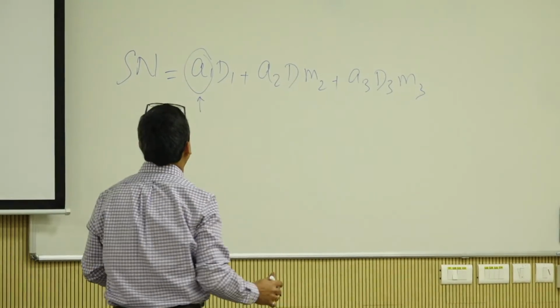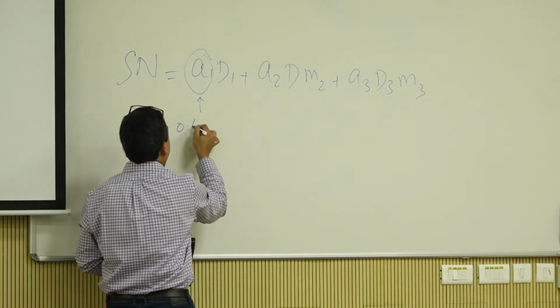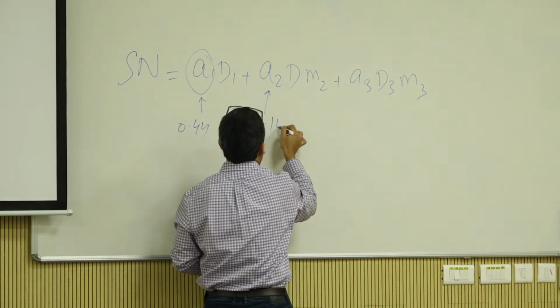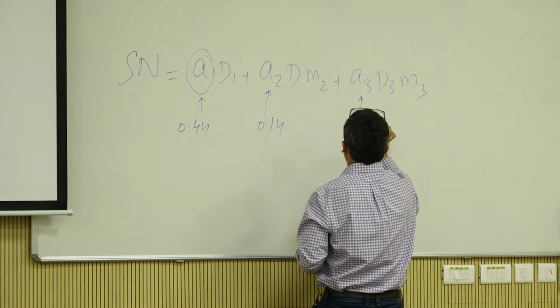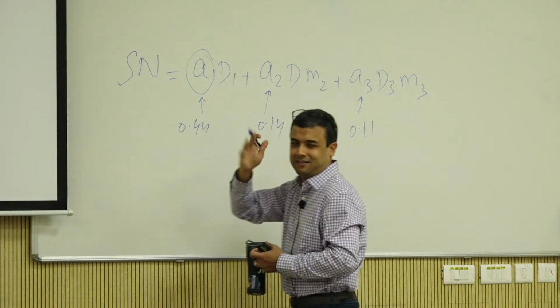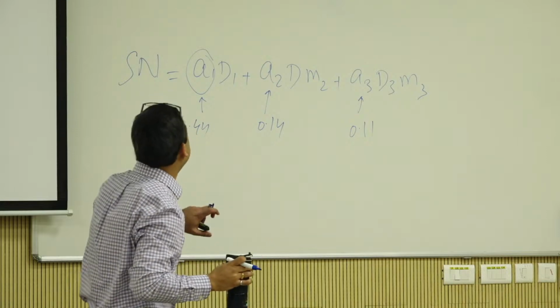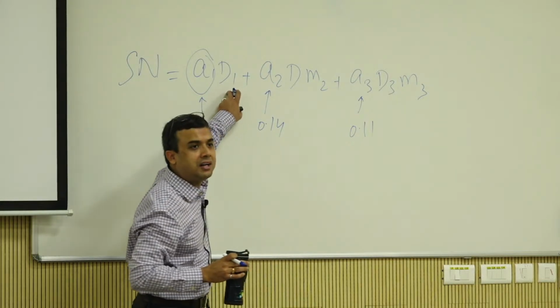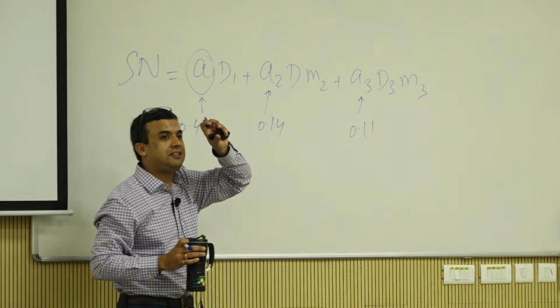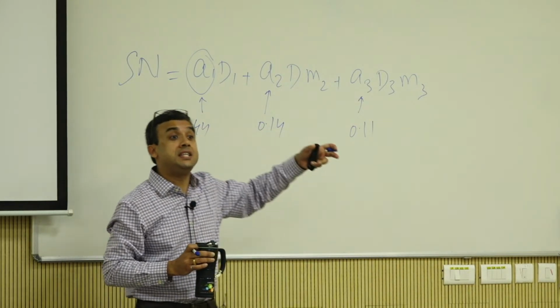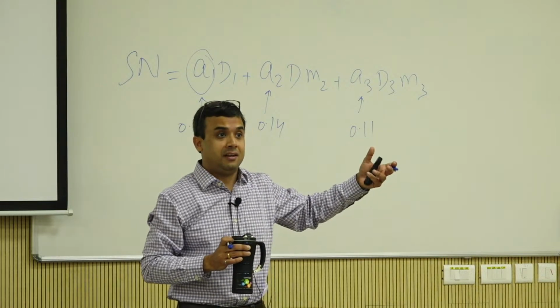That one is for asphalt, it is 0.44, something like that, and for base and subbase it is 1.08, something like that. So you are saying every inch of asphalt has this structural coefficient of 0.44. So if it is 2 inches, it is 0.88, right?